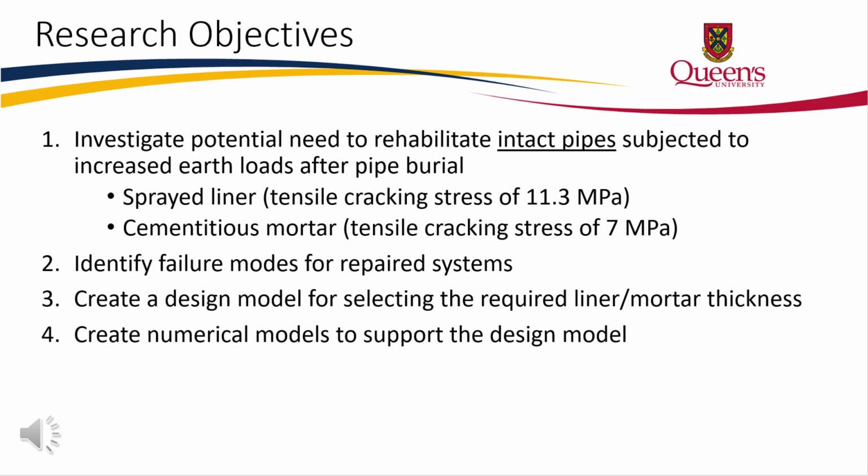Our second objective was to identify failure modes for the repaired systems. As noted in previous slides, bending moment is the critical failure mechanism in rigid pipes, where peak bending occurs at the crown. The bending moment induces compressive stresses towards the pipe exterior at the crown and tensile stresses towards the pipe interior, which may result in cracking. That said, we are looking to determine whether cracking due to bending occurs in the liner or the concrete pipe first. This is explained in more detail in the coming slides.